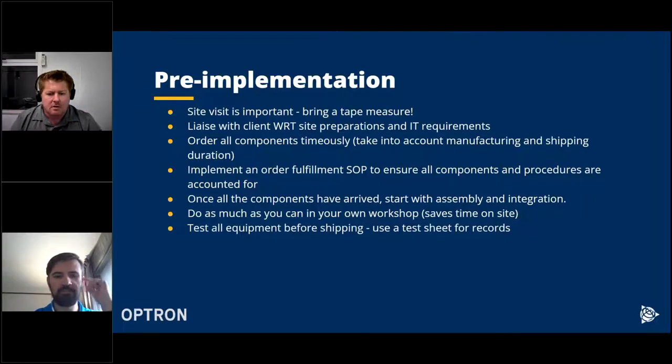And then test all the equipment. I guess you know that everything is working together once you've set it up, right? Before you get on site and it's 40 degrees Celsius or something. Exactly, because if you build it in your own workshop, it allows you to test the equipment before you ship it. And we've implemented a test sheet, so we also have a list that we run from the top. We test the voltages. We let the equipment run for at least 24 hours, what we call the burn-in, to ensure that all the electronic equipment is nice and stable and in working order.